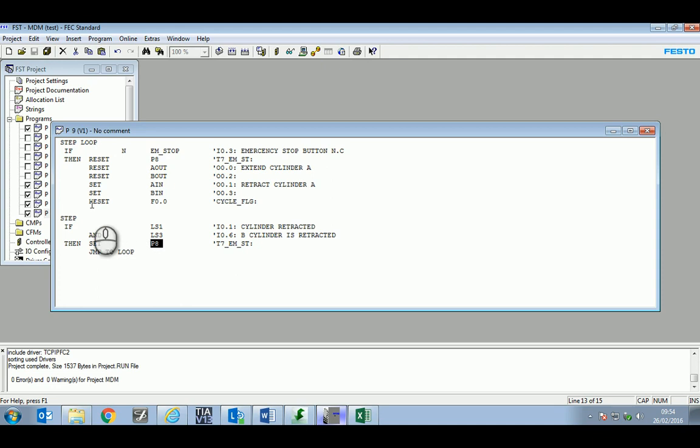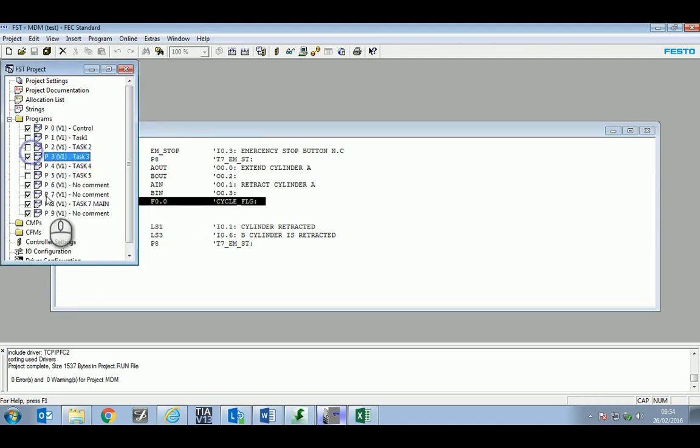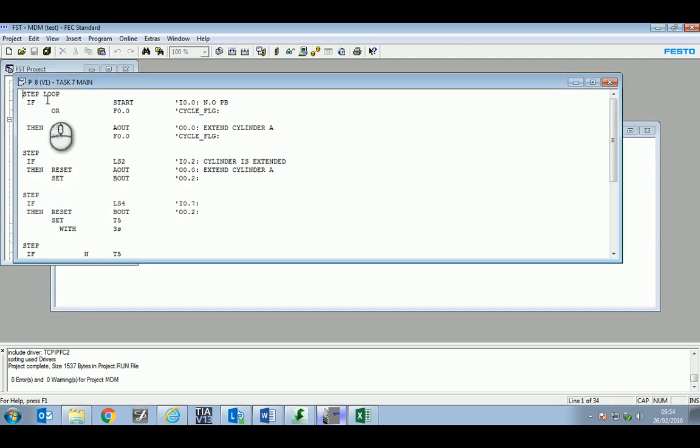That's why we turn off 0.0, which means when you activate P8 again, it starts here, and it's then basically waiting for the start button to restart again. That's you really back to the very beginning. So you now have two options to control this. You press start, and it starts cycling through. If you press the stop button, it finishes its cycle and then just stops at that point, waiting for the start button.